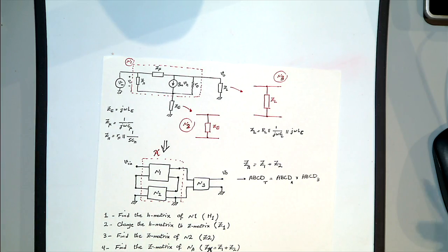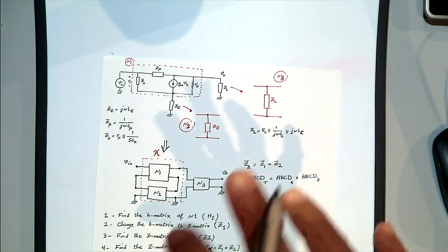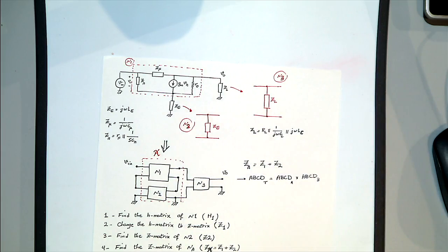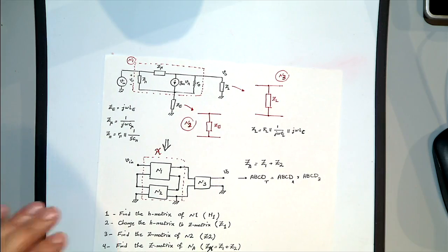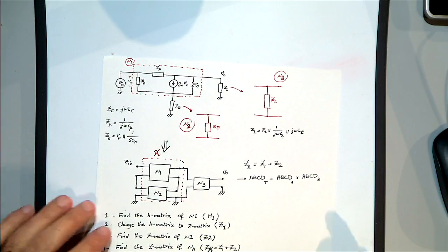And depending on which one is more useful in our circuit, we can pick one, and then we can transfer them to each other. I mean, if we have the Z parameters of a network, then we can simply, by the table, move to the ABCD. Or if we have Z, we can find the Y. Or we have H. All of these are transferable to each other. Okay?